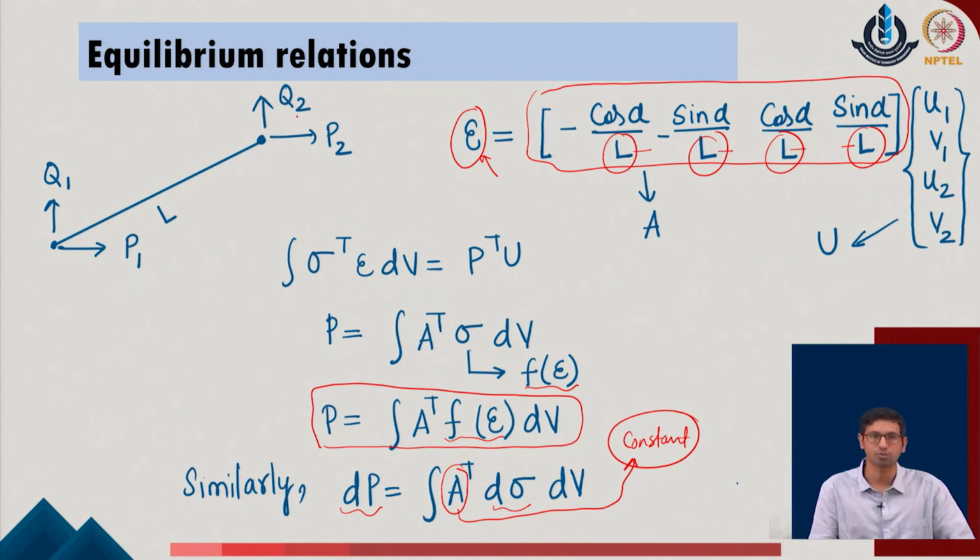which will be available at the nodal points of the given system with respect to any change in the internal stress component is now known to the user. So, what user will do now, at any point of time, of course, at the external nodes we are trying to provide the load increments in the given system, that is how the simulation will start, but at the same time the tracking of the nonlinear relationship of the material rule will be done with the level of the stress increments in the given system. So, that is where we need to now make a balance between the external load increments as well as the internal stress related changes which are appearing in the given system.